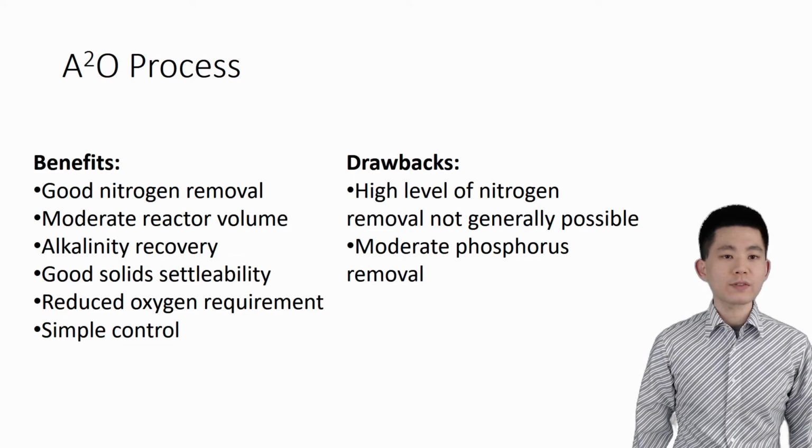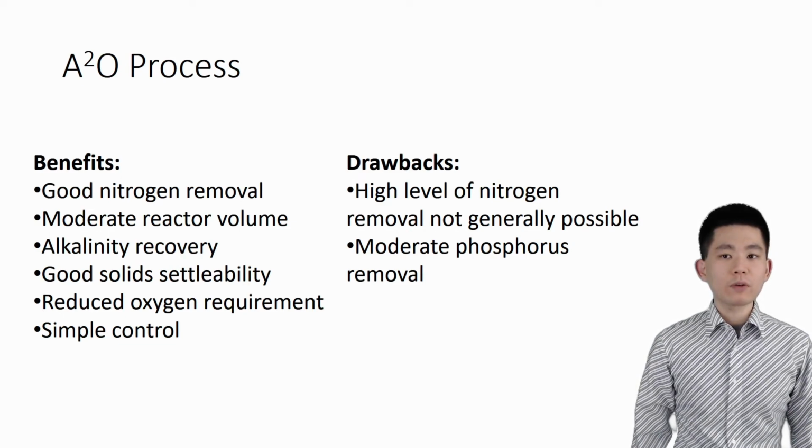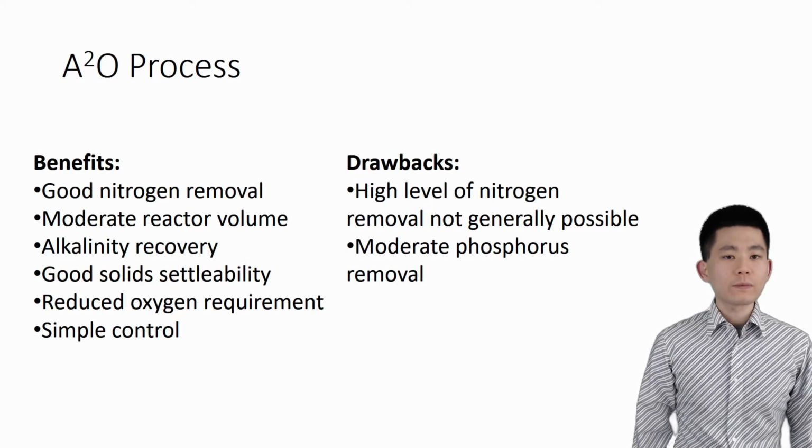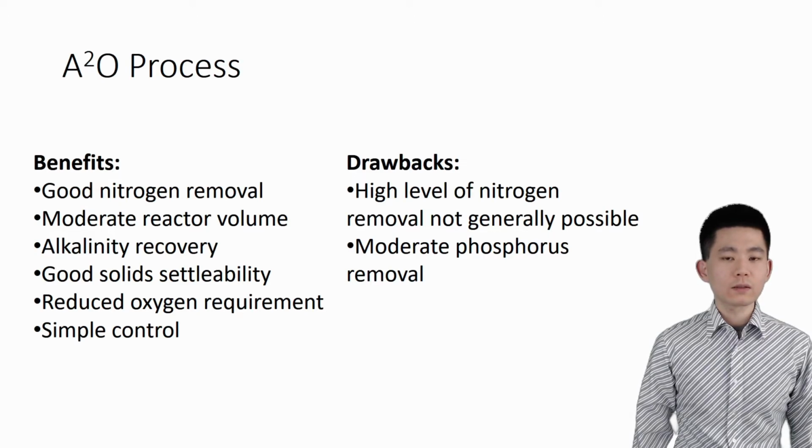The A2O process has the same drawback of incomplete nitrogen removal as the MLE system because a portion of the nitrate is discharged from the aerobic zone without denitrification. Additionally, nitrate is also present in the recirculation biomass flow to the anaerobic zone, reducing the VFA production from fermentation, and therefore the phosphorus removal efficiency, especially when there is not sufficient soluble organics in the influent.